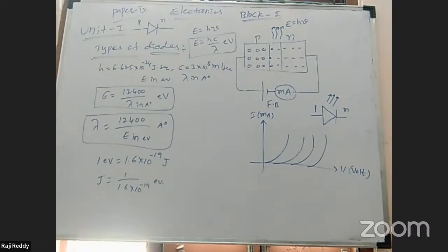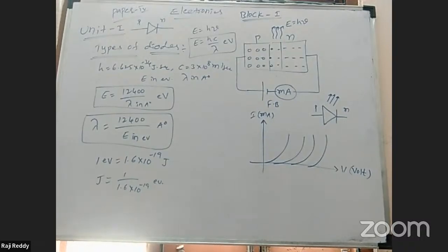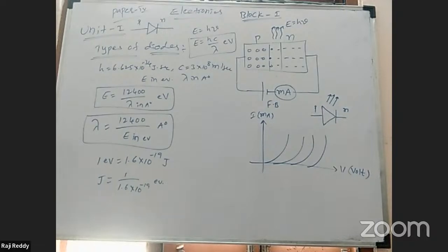The thickness of the P region is kept very small so that electrons generated in this region can diffuse to the junction before recombination takes place from the N region. This is the construction of the solar cell. Once go through it in your material, page number 9.